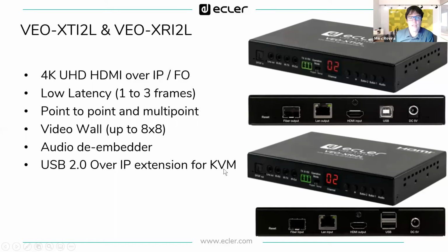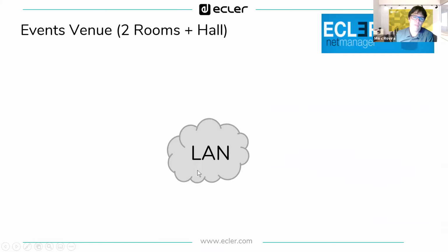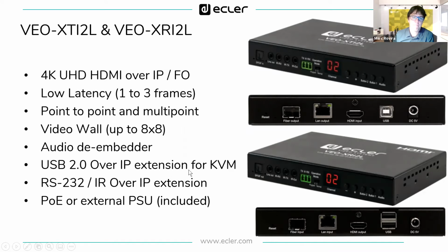It's a KVM extension, from here or here. And it also has RS-232 and IR extension. You can also send RS-232 messages to other devices. Sorry, it is PoE as well. It has an external PSU included, but if you want to use PoE from your switch, you can use it.